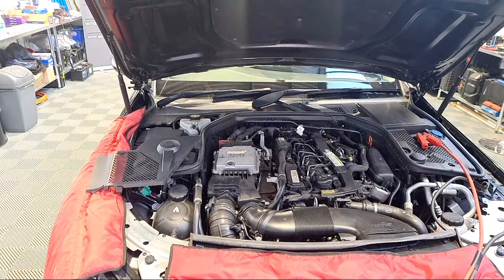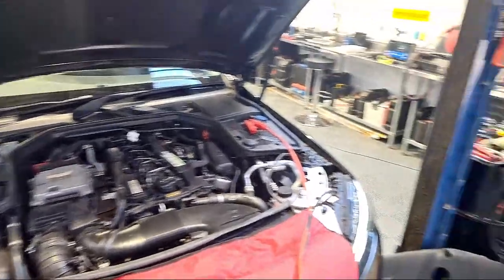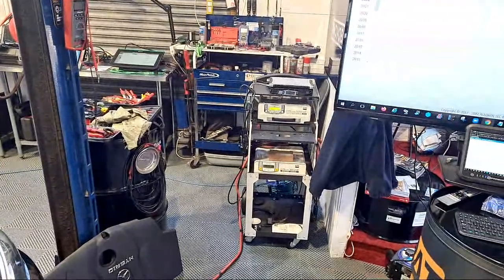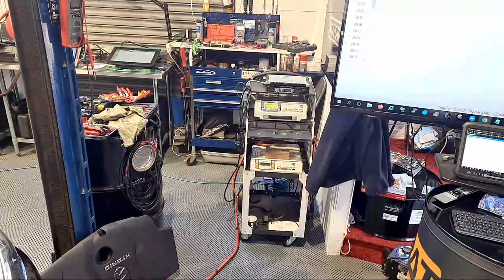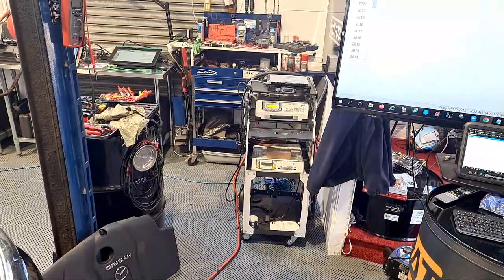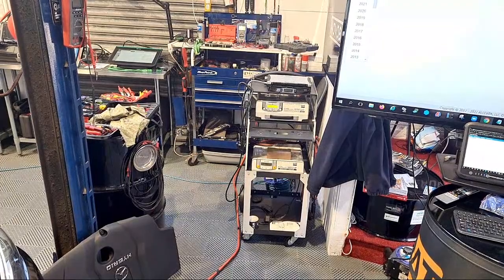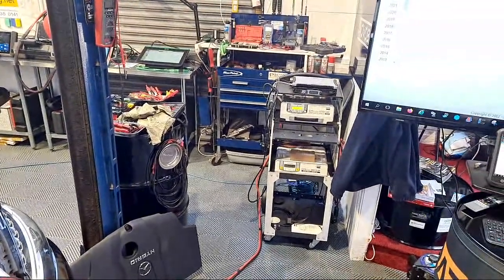So we've got it set up. We've got the KTS on it. Morning, Stephen. We've got the KTS on it. We've got the GYS battery support plugged into it and turned on. And that GYS now is currently running at, with the key on, 18 amps. And there's 18 amps going in that just with the key on.